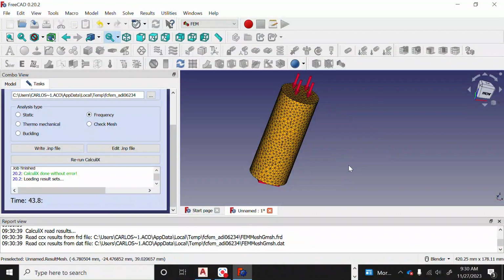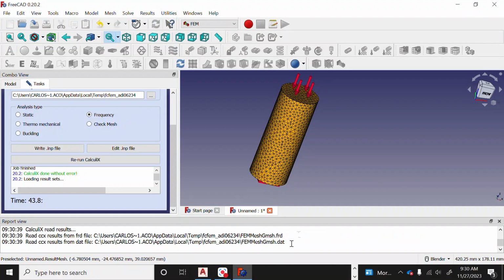So this is a very useful input file. As long as you have access to the input file, you can redo the study and change the material properties from the file. Check the last video and you'll see how to access the input file, and you can change the density. You can change mostly anything, even the mesh, the boundary conditions, the amount of forces that you put.